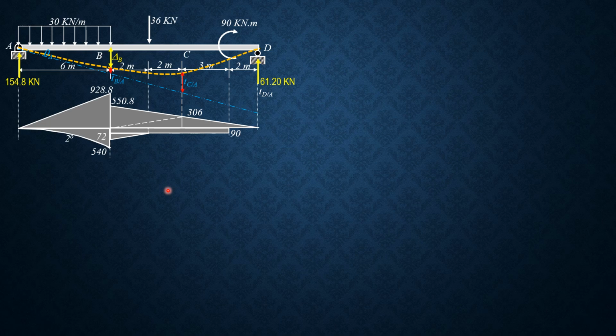So we again remove supports at B and C. Then we make B the moment center. Then the supports would be the same, pin here and roller there. So call that theta A. Then we have theta B later and deflection at B later for our analysis. But let's solve for theta A first by summing up moments about D equals 0.